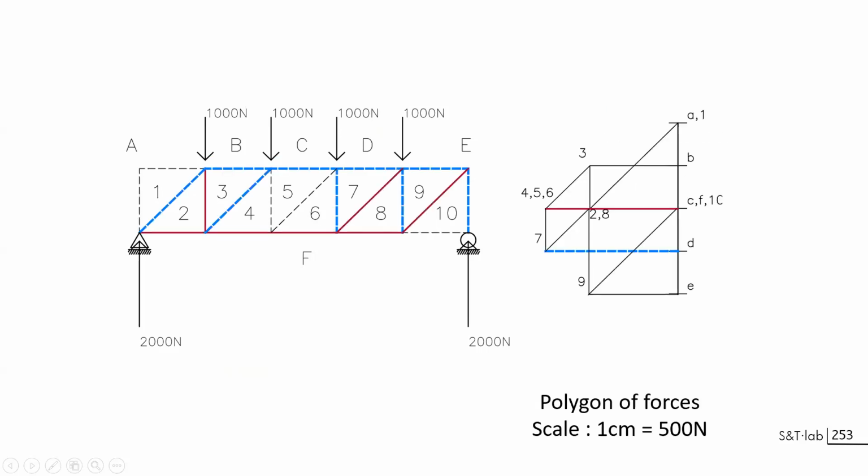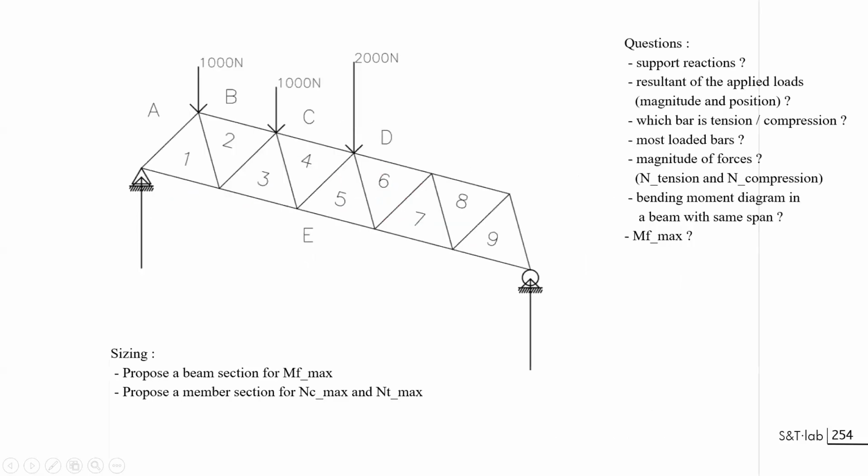Going to the solving of this truss, we show you where the bars are changing direction, so diagonal will be equal 0 here, and diagonal with change of sign becoming tension. Hence, it was compression in the very beginning. So that's the approach. At the end, you have a system that you can solve completely, and that's a kind of summary before going to applied cases and hyperstatic cases, in which you have a kind of truss that will be inclined, that can be considered as a beam.